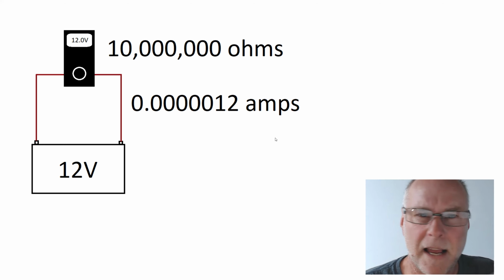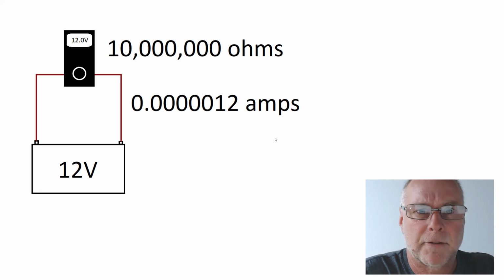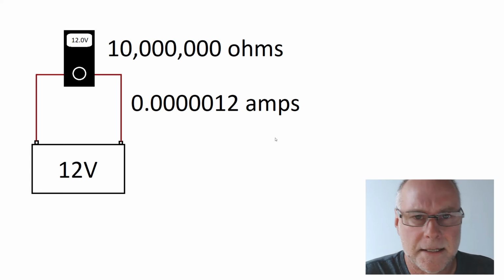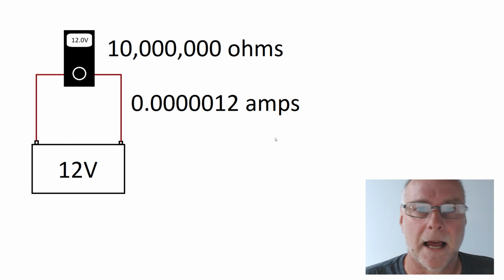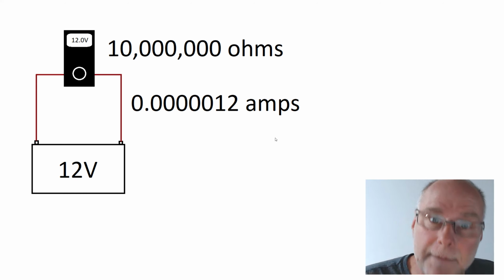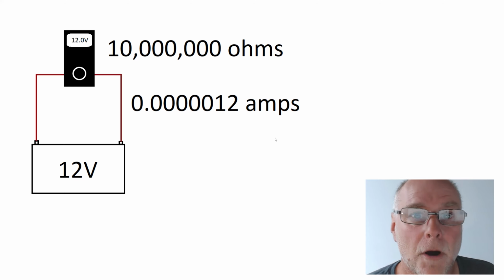And some people will say, oh, but you're just connecting it across the battery. That's a short circuit across the battery, isn't it? Won't the current destroy the meter? And of course it doesn't, because the input impedance of the meter is so high.